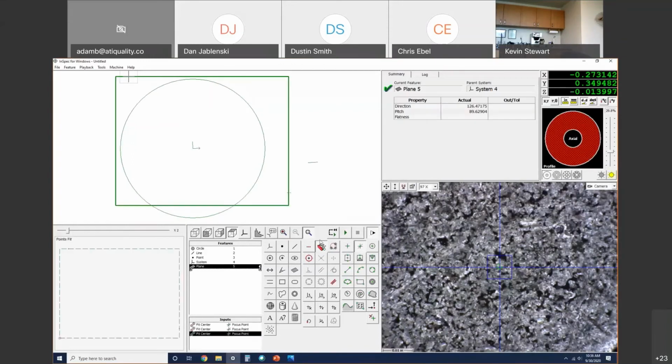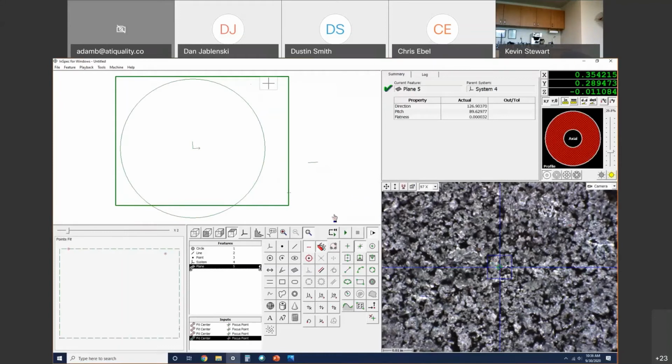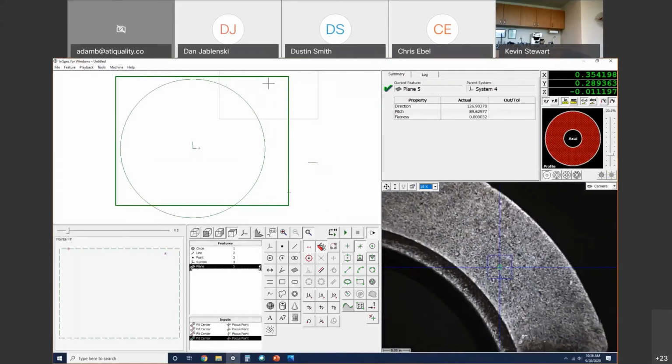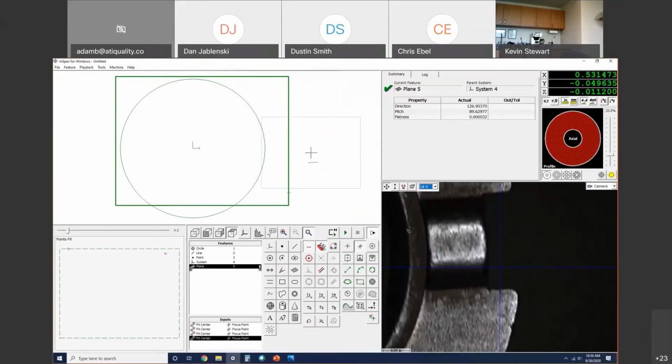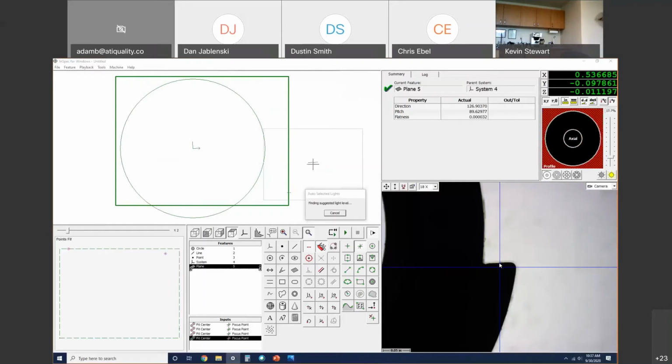Now we got our plane. Because this plane is a datum, I want to take at least 4 points around this surface just to really control that and make sure that I'm getting an accurate datum setup. Now I am going to come over and take more accurate and repeatable, is key, skew setup here.